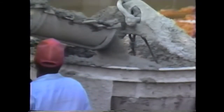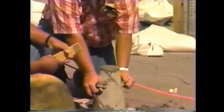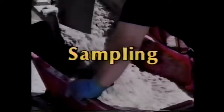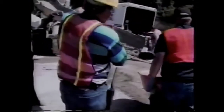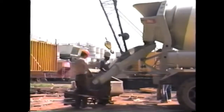So it's important, and it's required, that the quality of the concrete be verified before the concrete is cast. Verification is provided by conventional controlled tests performed in the field. Our first topic then is sampling. Before any of the tests can be performed, a sample of the concrete is needed, a representative sample. The concrete to be tested has to be typical of the entire truckload.